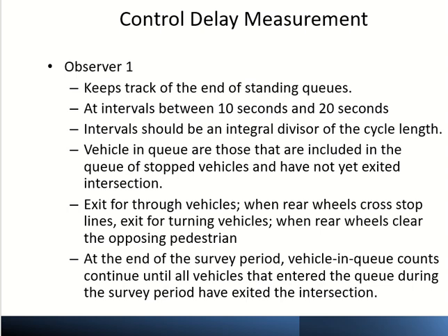Now one more thing, which is the end of the survey, the end of the study for this guy. There will be a time given to this guy when he is supposed to finish. Okay? But we said we don't like him. Okay? So what do we do? We tell him, okay, when you are finishing and there are vehicles in the queue, let's say there are 2 vehicles in the queue, you will continue this study until these 2 vehicles leave.